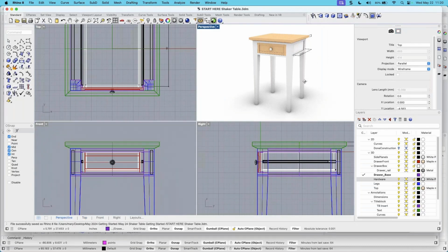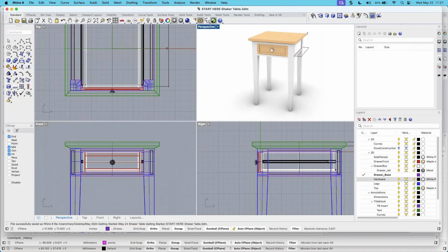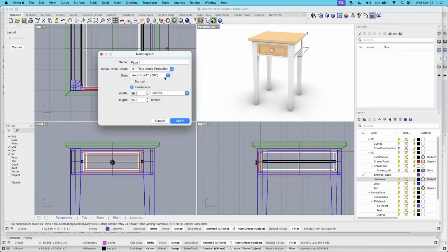And I went ahead and saved this. Probably should change the name, but I can always unzip another one. I'm going to go to Layouts and Plus, and I'll add a D-size sheet. If you pick here in units for millimeters, you can see 914.4 millimeters by 609, that's our size in inches, which is a 36 by 24.